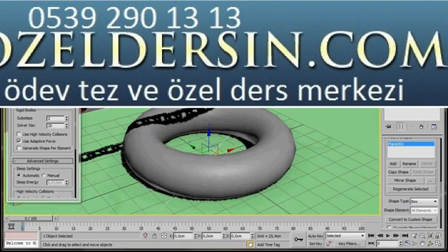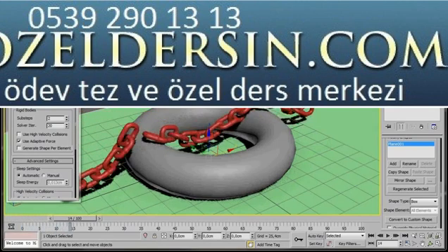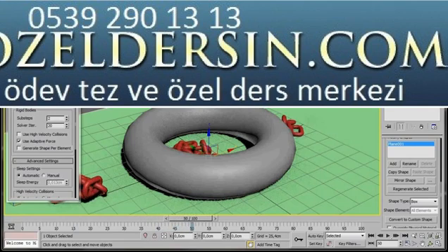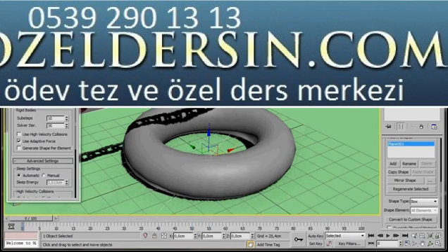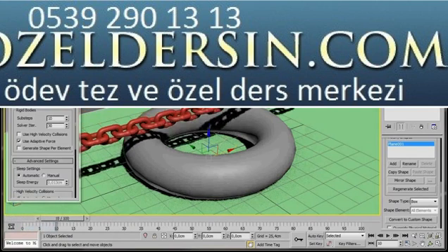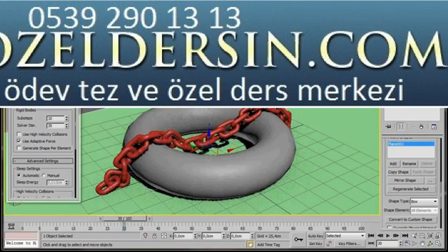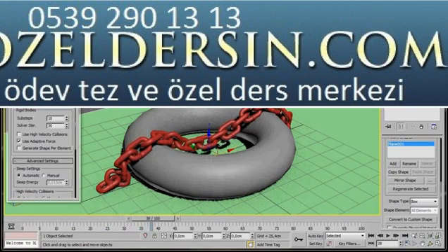Now let's press the play button. It's still breaking apart, but we're getting there. Let's come back over and adjust our sub-steps again. This time I think I'll bring them up to 10. And in the solver iterations, I'll try 30. Let's go back and press reset and then the play button again. Now that's worked. Notice how each link is individually moving and twisting.